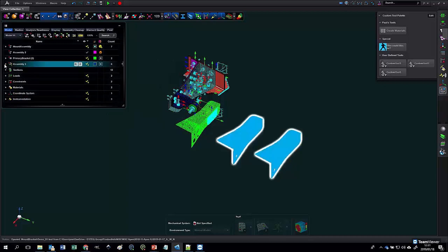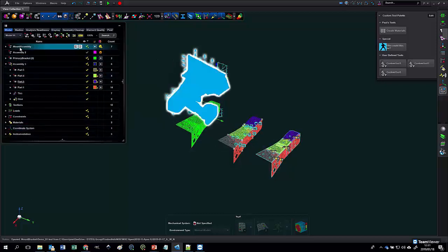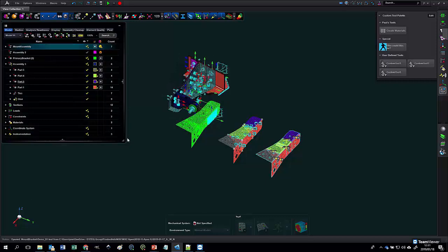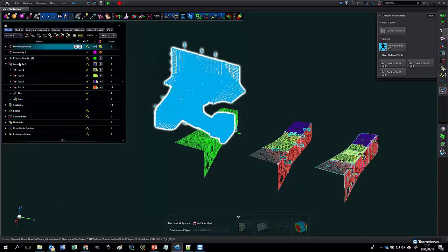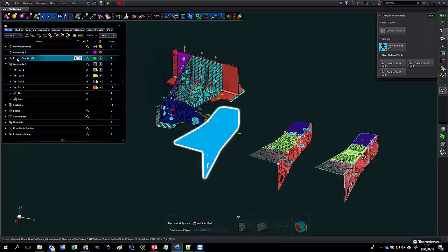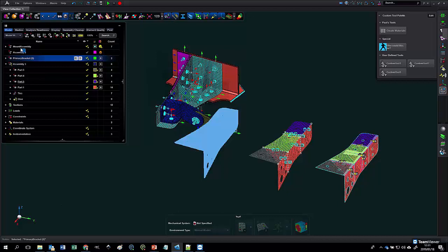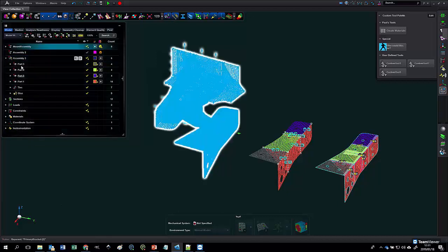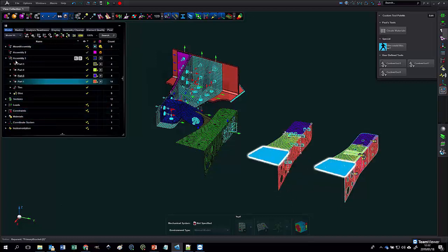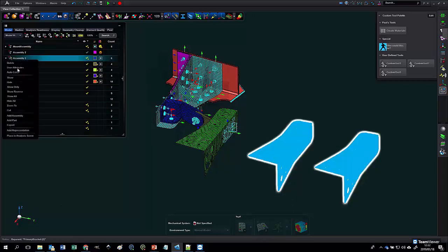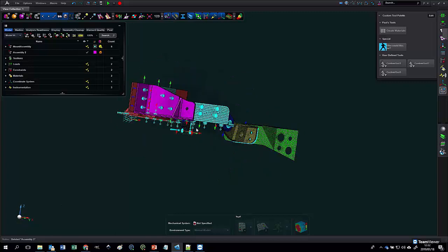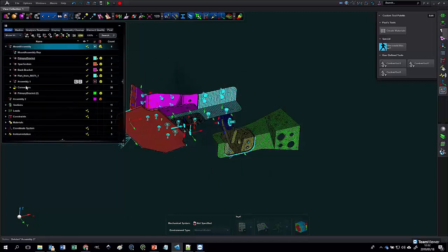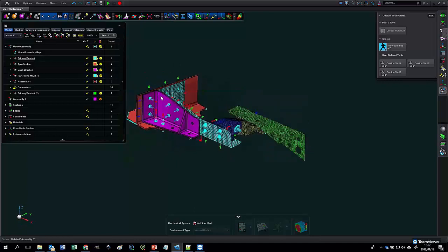Okay, so firstly, I did show briefly how to set up model representations. As you saw previously, you can have multiple assemblies inside your model and reorganize them any way you want. So I think what I'll do is I'll make that part of the original, and I'll just ignore those guys. Let me just delete them for now and work with this assembly. So we have this capability to solve sub-assemblies or parts individually, or we can create model representations.